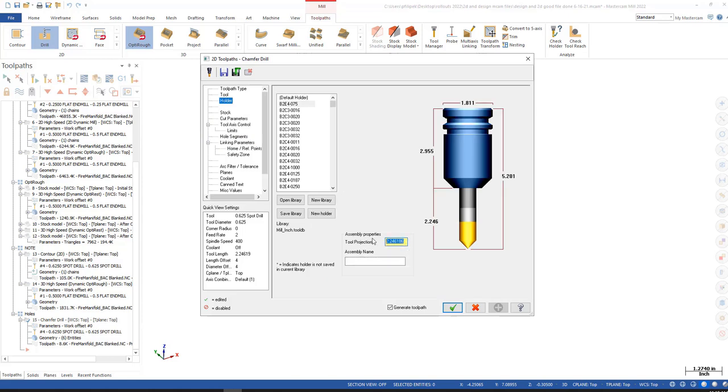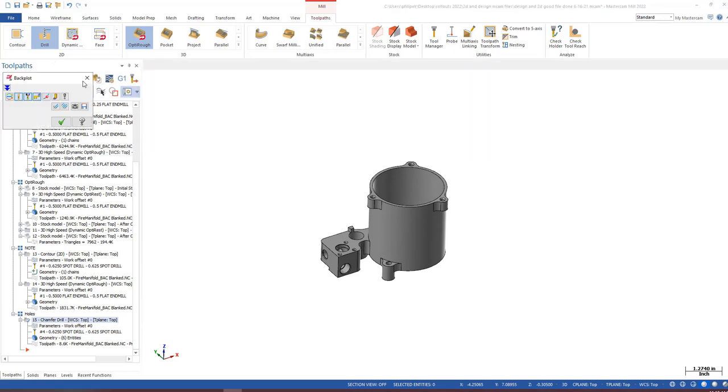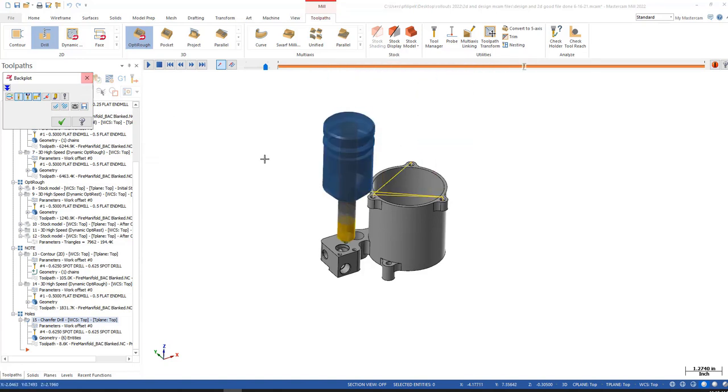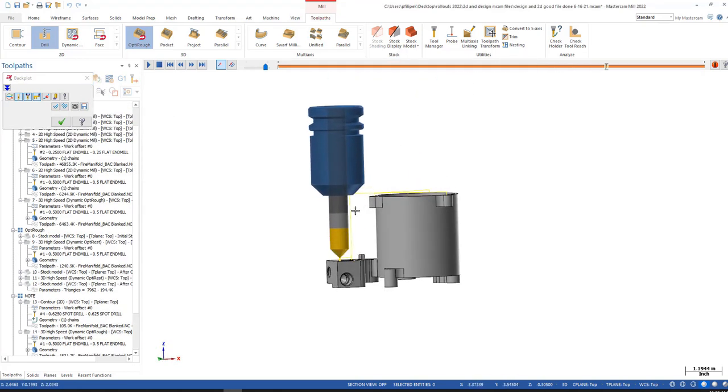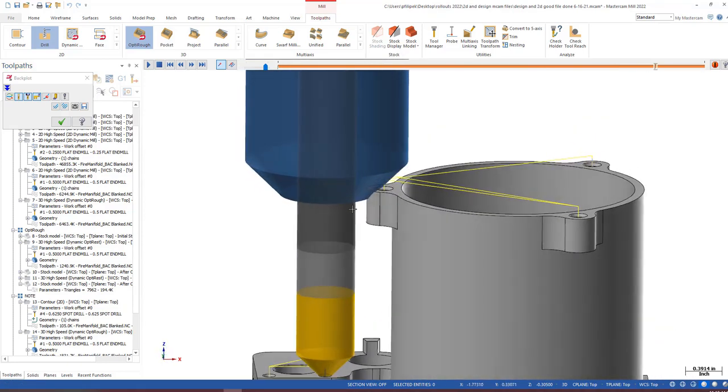I'm just going to set my tool projection at 2.1 inches. So I'm telling my tool to hang out 2.1 because I have no idea what I need for projection with that holder. Now if I come in here and backplot this, it's going to do its drill tool path. And we're looking good here so far, looking good. And we're not looking so good there. So we have a collision with the holder.